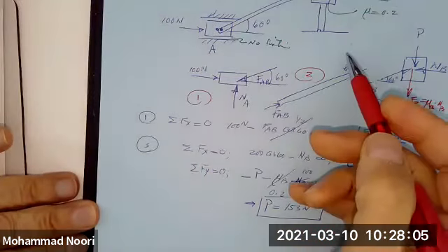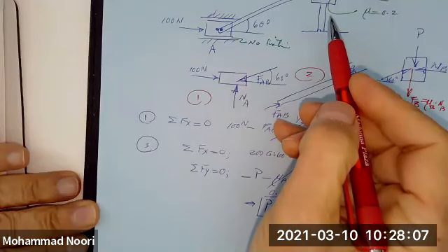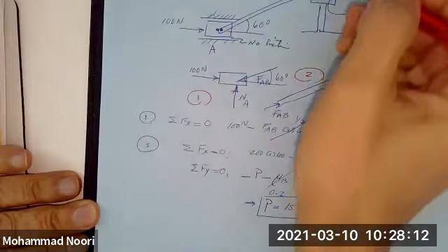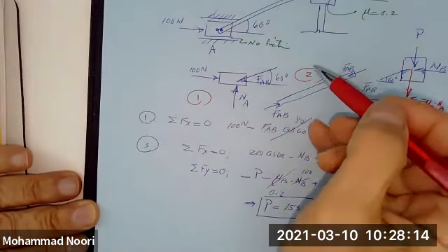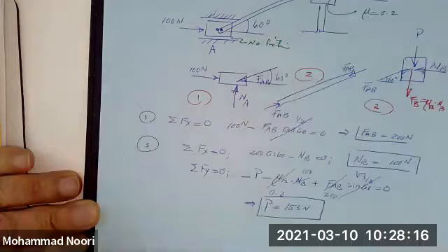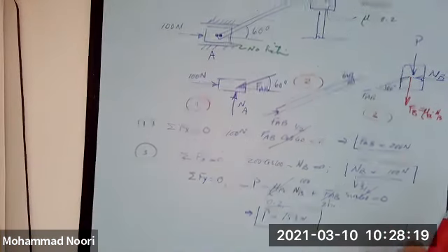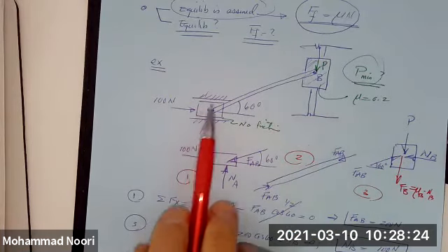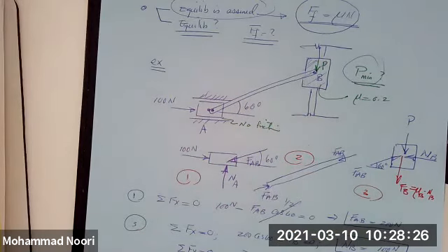When it's a friction problem, do you not need to draw the forces on the entire free body diagram, like the whole system free body? The whole system? Well, the whole system, you cannot have the free body of the whole system because it's an infinite rod. We don't know what the connection here or what the connection is here. So therefore, you only have 3 free body diagrams of the 3 pieces. Okay, thank you. Sure. Any other questions?